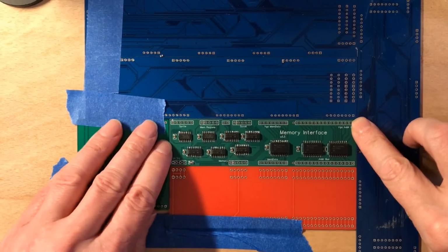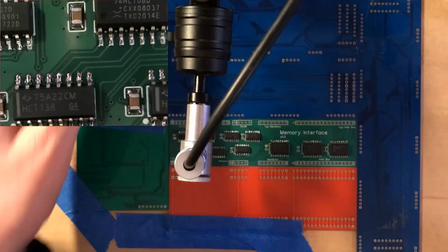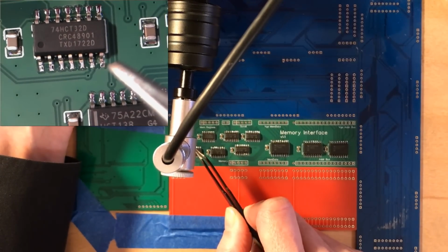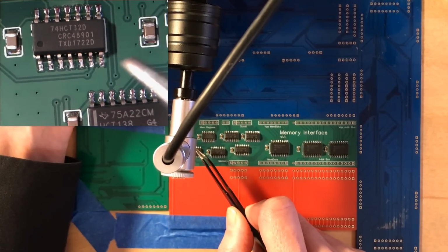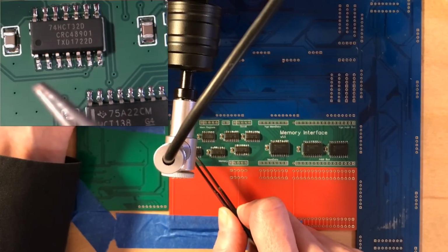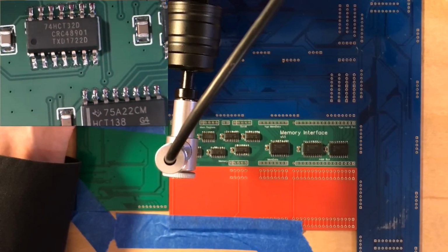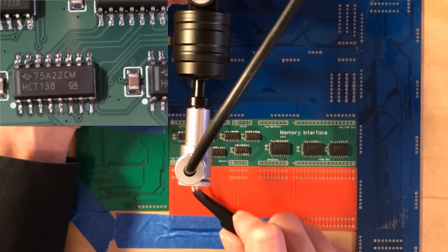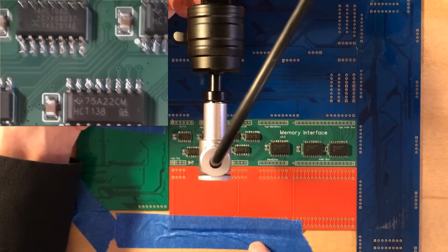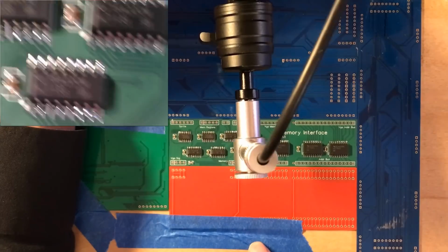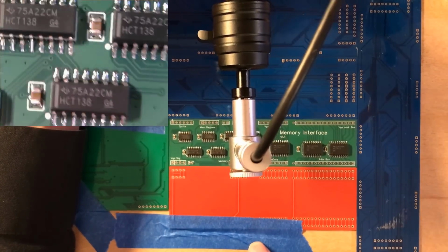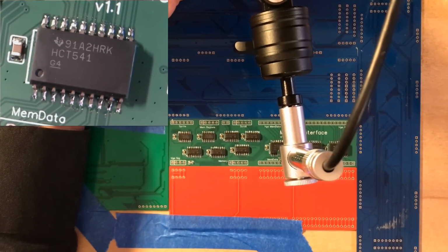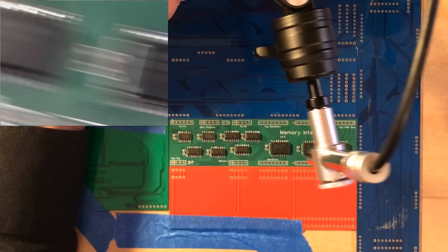Let's get a look at this. Now, these ones at the bottom here, this is twisted slightly, I think. These ones at the bottom here, it's not obvious if they've connected or not. They're probably fine, but they're suspect. Similar thing here. I'm a little bit worried about this solder. It's maybe dried out slightly. Caps look okay. That solder's at least cleared away nicely.